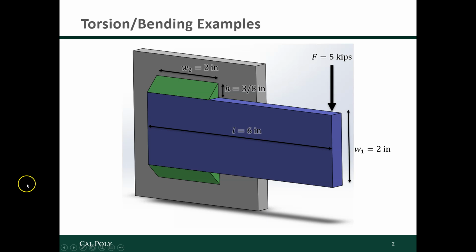That's what we're going to learn, and we'll do it through an example. So here we have a steel bar that's 6 inches long. It is 3/8 of an inch thick and has 3/8 inch fillet welds. If the force were applied in this direction and it was straight through the center here, then it would pass through the centroid of the weld, and so we'd just call it a parallel fillet weld, and that would be a parallel loading. But now we've got a force that's applied at the end point, and it's going downwards.